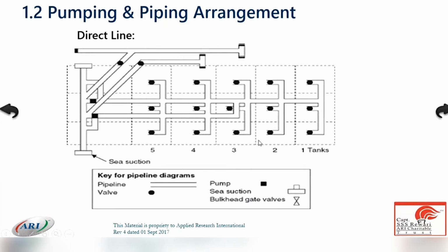If you remove all this in a free flow, what happens? There's no pipeline here. Only the pipeline is installed on the last set of tanks and is connected to the pump room, and you have the manifold for discharge. And these pipelines are non-existing. There's no pipeline on any of the cargo tank. There's no bell mouth. So just imagine there's only pipeline on last set. This pipeline is existing, and there's a pump room and there's a manifold. There are no pipelines forward of this tank. Number 5 forward, there are no pipelines at all.